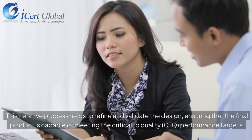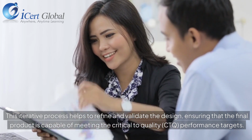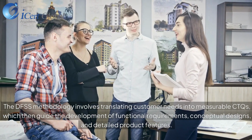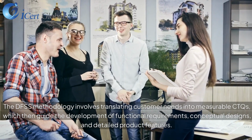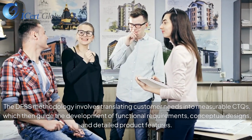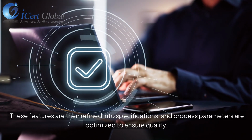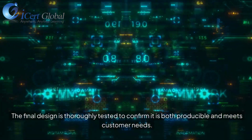This iterative process helps to refine and validate the design, ensuring that the final product is capable of meeting the critical to quality (CTQ) performance targets. The DFSS methodology involves translating customer needs into measurable CTQs, which then guide the development of functional requirements, conceptual designs, and detailed product features. These features are then refined into specifications, and process parameters are optimized to ensure quality. The final design is thoroughly tested to confirm it is both producible and meets customer needs.